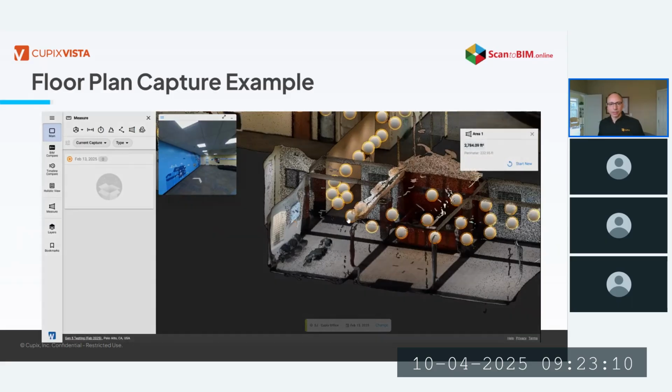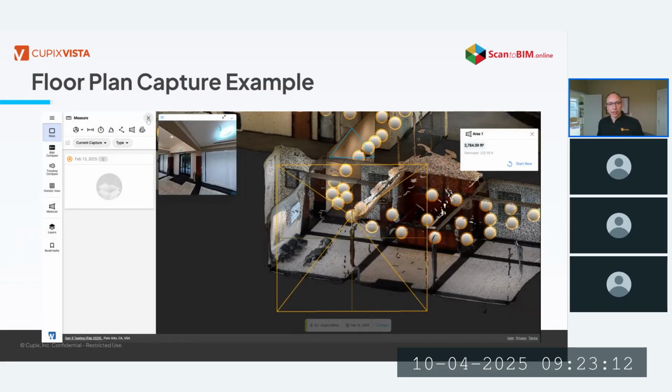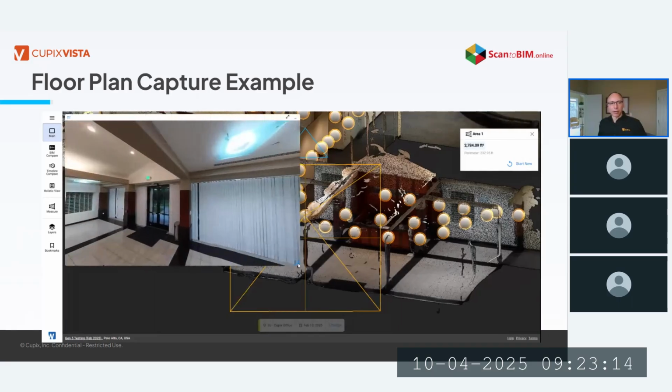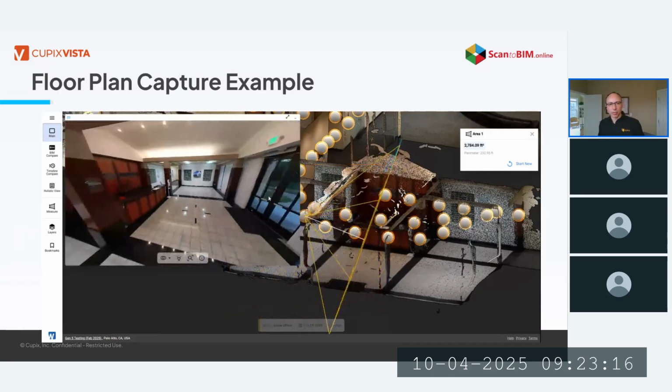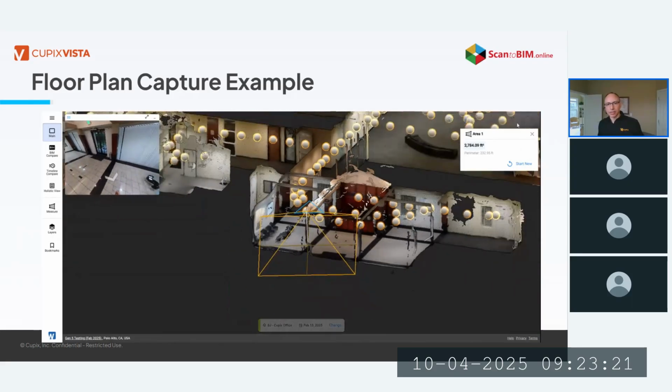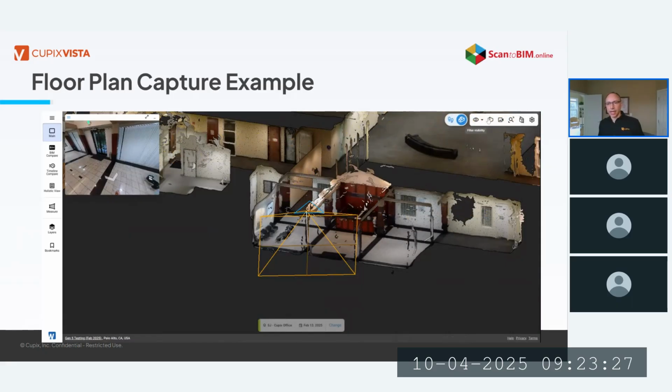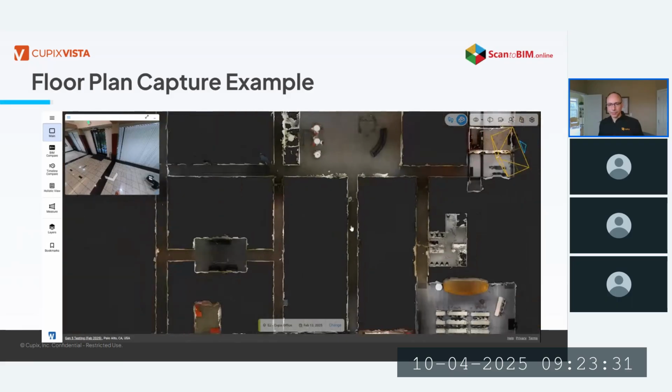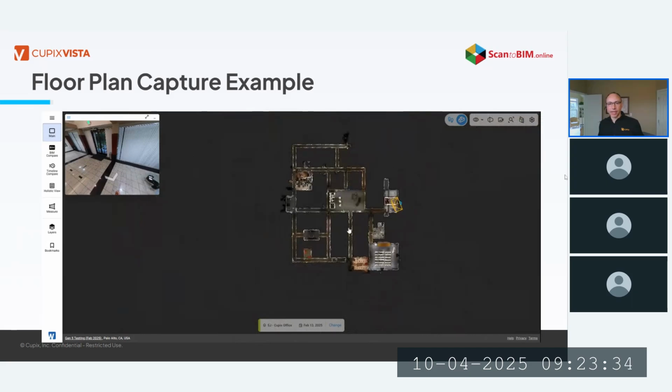And then you can hide and bring back the pano bubbles, and it allows you again to just explore what's really there. And this can help in the Scan-to-BIM as well, because sometimes if a detail isn't clear in a 3D, you can look at it in the picture and understand what it is, and construct a BIM element based on that as well. So it all adds up to really having a full understanding of an as-built condition.